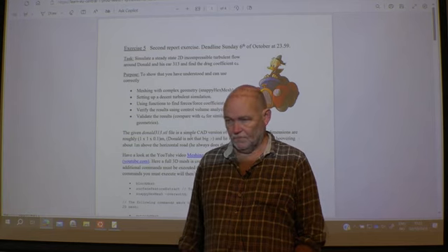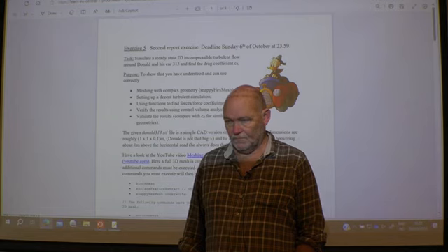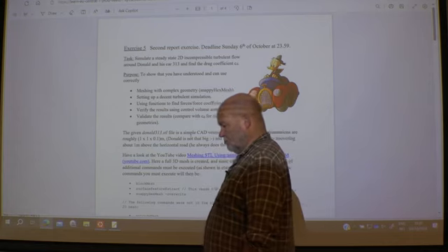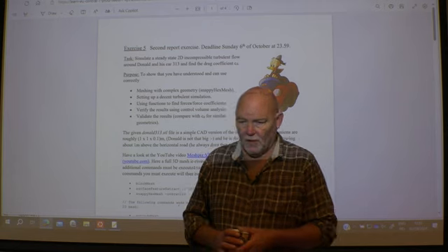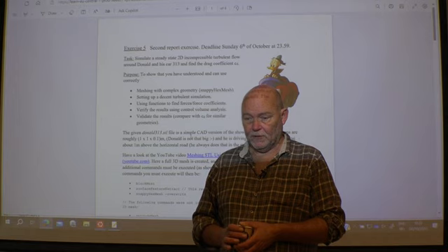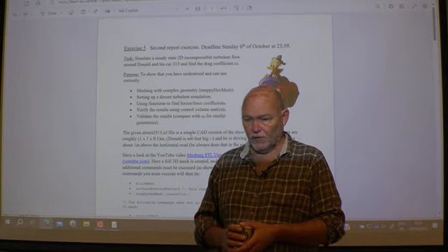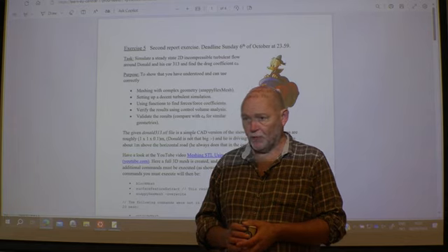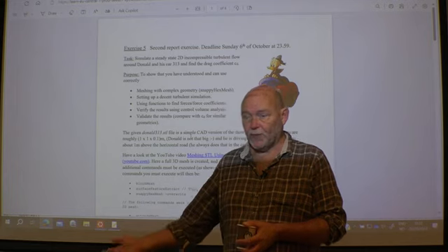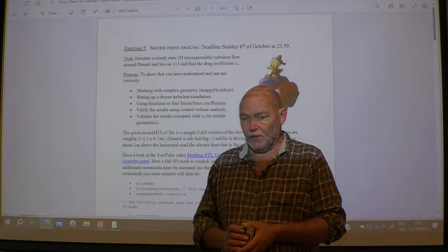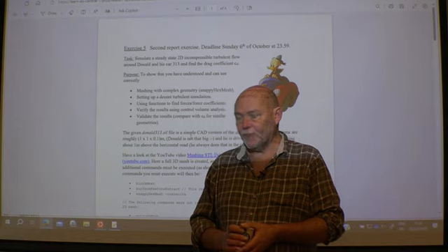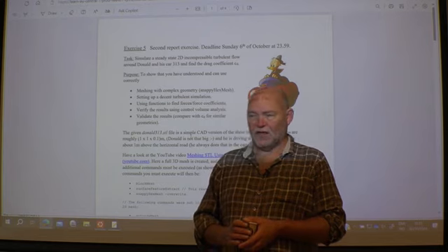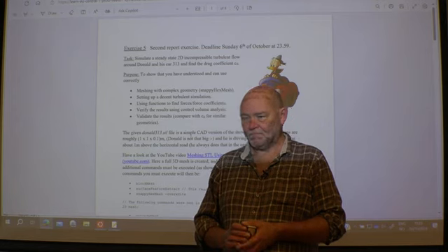Yeah. I tried running it in parallel, and then it crashed because the mesh was bad. Does parallel have any extra requirements for a refined mesh? Or is it just that it crashed faster because it's faster? Yeah, it crashes faster because it runs faster. So it doesn't change anything logical with the mesh when you run in parallel versus on one CPU. That shouldn't change anything. You should get the exact same result in the end. So the reason that it crashed is you have specified too high a degree of detail, I guess, and that's fairly dangerous. But no, it shouldn't take hours. So don't overdo it.